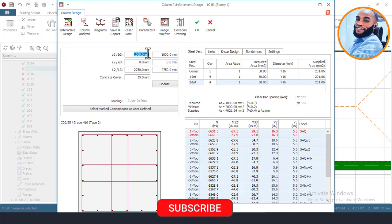At least use something that is adequate. 25 diameter bar is not really that much for a high-rise building. Any client that can afford to build a high-rise building should be able to afford 25 diameter bar. And also, since it's a high-rise building, you need a bigger diameter bar like 25 and 20 to be able to carry the load efficiently. Although, I'll just give you my own advice on that.